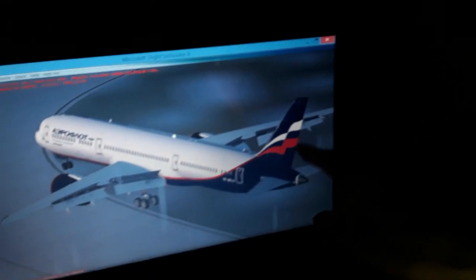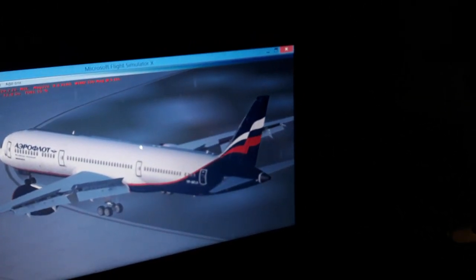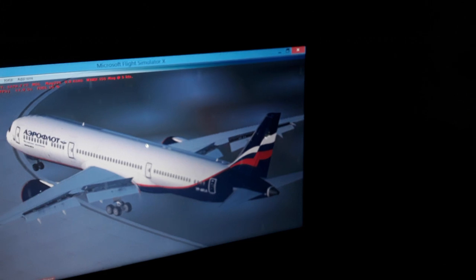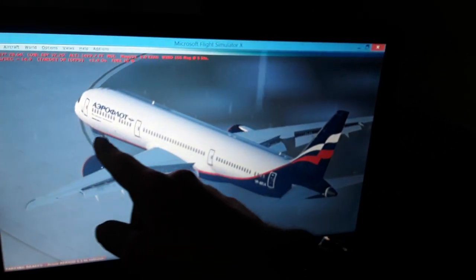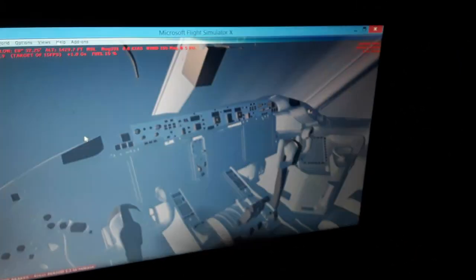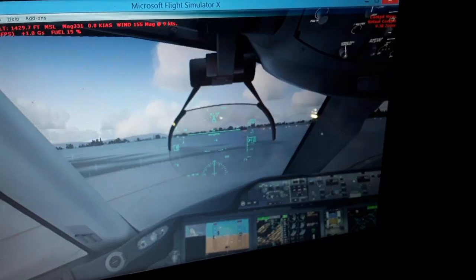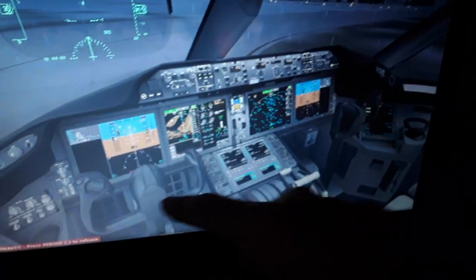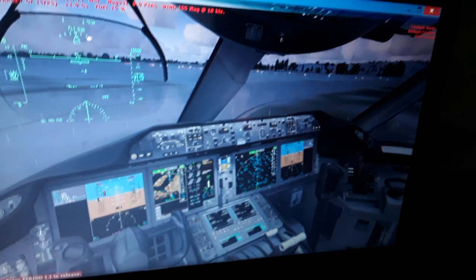So in landing, when we land, we start with the rudder because we have higher airspeed, like 140, 150 knots, like 250 kilometers an hour. So it's the inverse. First we have the rudder, then the nozzle becomes active. Also sometimes the nozzle is active, with a small amount of deflection, like a half degree above 80 knots or 1 degree together with the rudder. It's a very small amount. So this is the rudder control.